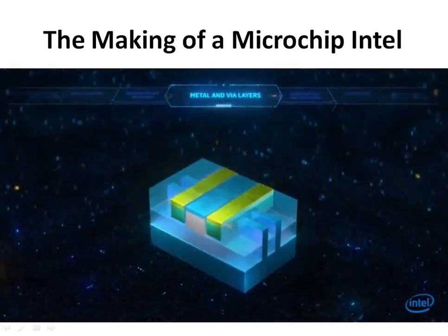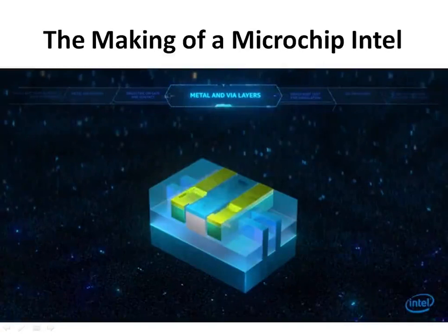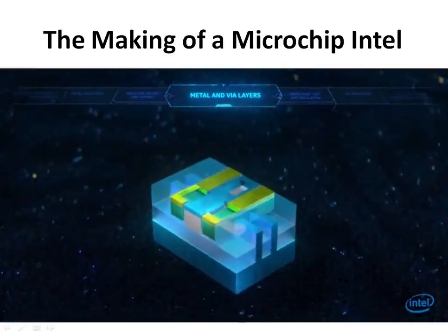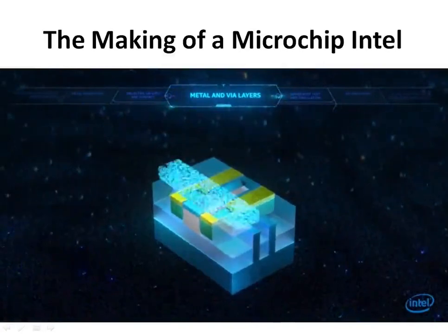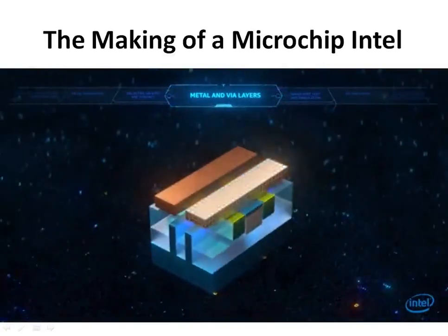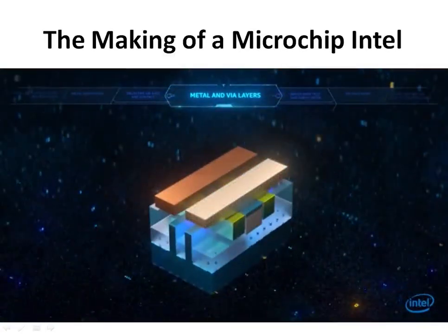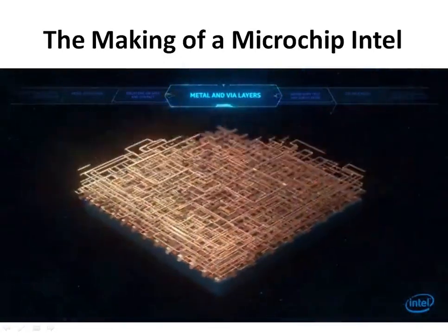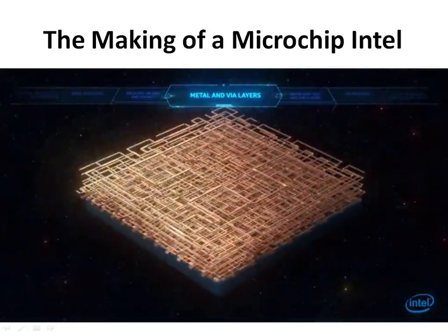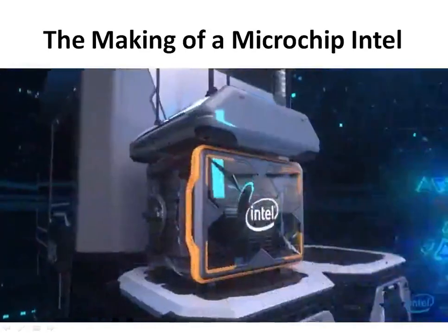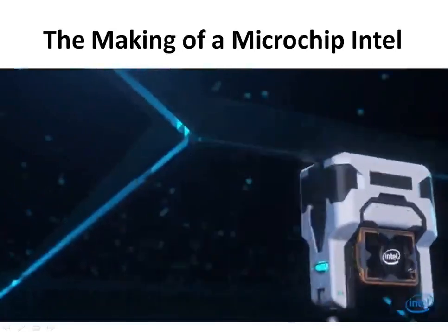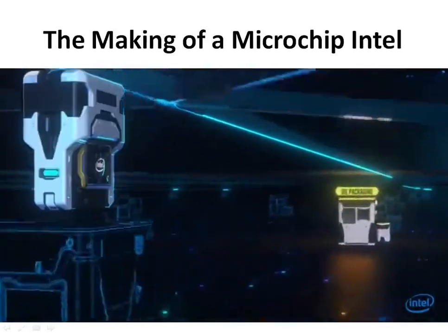Now, the dielectrics are etched selectively to expose only the desired part to connect to the first metal lines. This is done through an innovative via etch and deposition scheme, allowing contact over active gate to happen. Finally, dozens of layers of metal interconnect lines are added to complete the circuit. After more than 1,000 of these complex steps, the wafers are finally prepared for singulation and packaging.